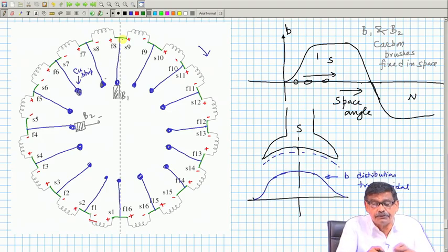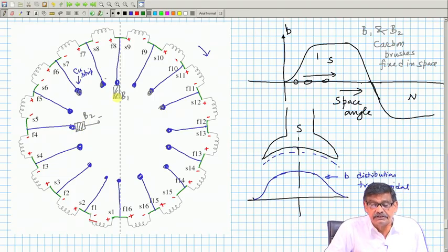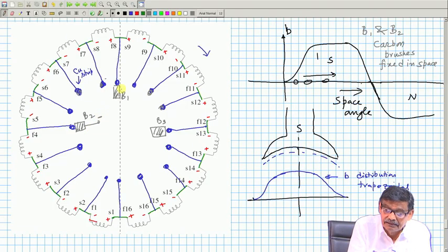So, from the junctions you have to drop out some wires, terminate some copper strips, and place your fixed brushes in appropriate positions and so on. Wherever it is plus minus, plus minus, plus minus, here also I could place a brush, very nice, a fixed brush, say B 3, because minus minus has joined. So, this is the negative brush, this will be the positive brush.